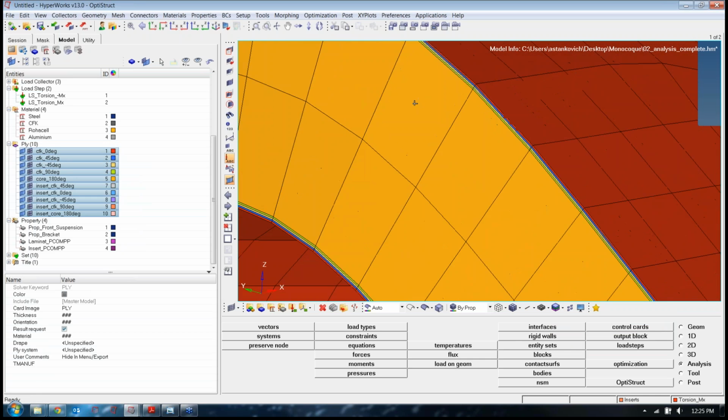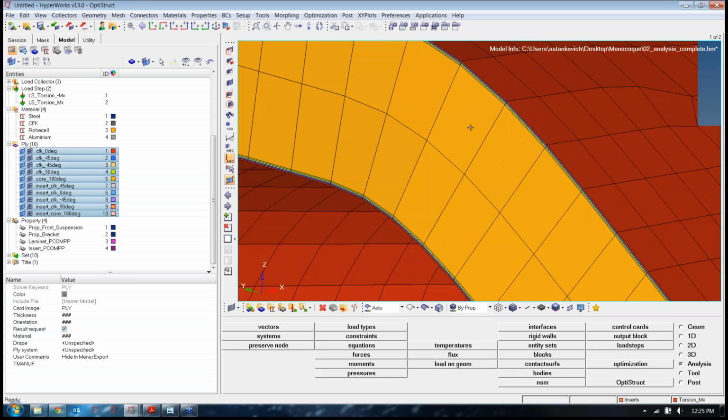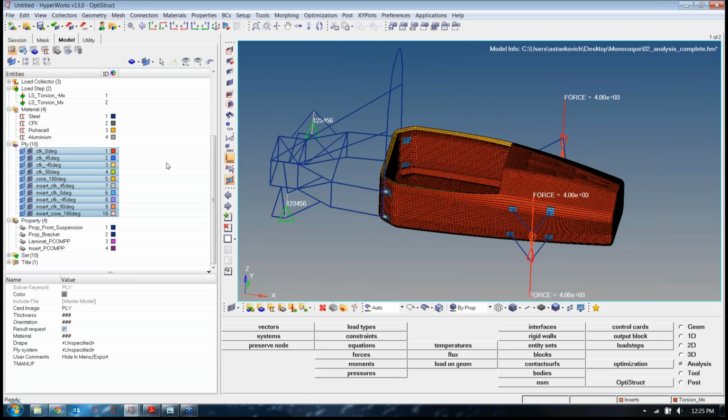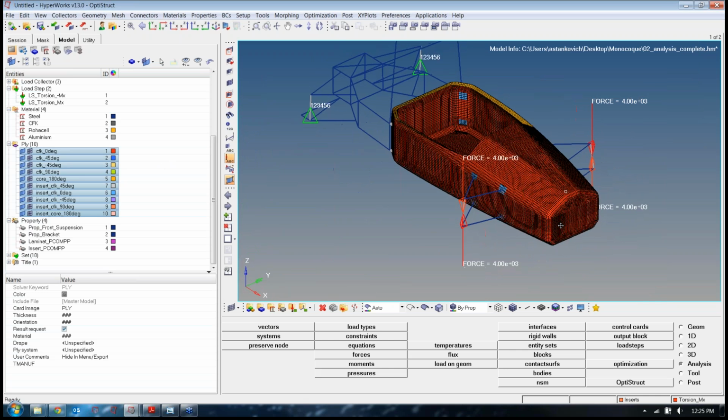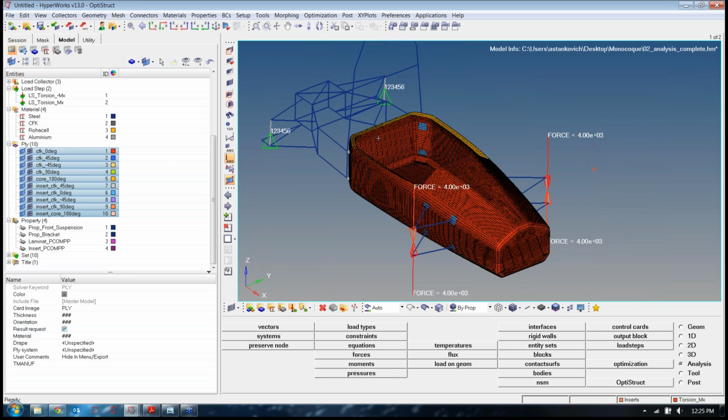And when I zoom in now, you can see that I have my core ply and then I have my 4 outer plies, and you have that on both sides due to the symmetric property in the laminate. So that's pretty much the basics of setting up a composite for analysis. If you're working with some type of CAD software where you've already designed a CAD product, you can actually directly import your plies and all of this and realize them in HyperMesh for your analysis.